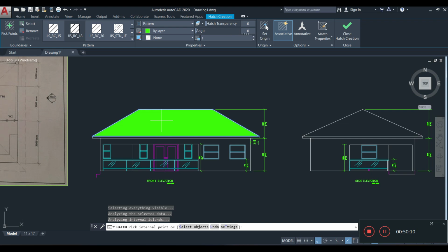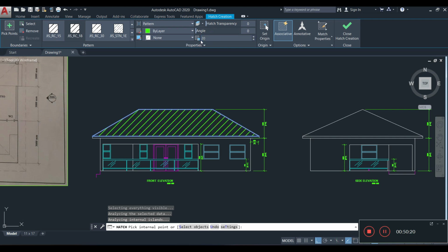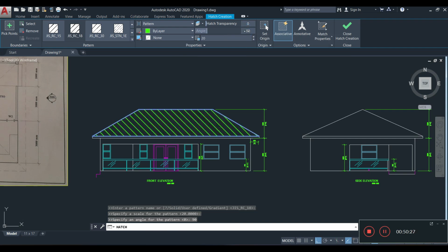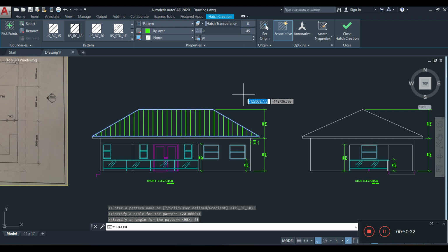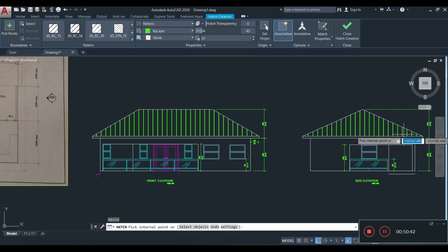Let's change the scale of this. Let's go 150. Yeah, that's too much. Let's go 20. Yeah, this can work. And the angle, I'm going to rotate it 90 degrees. No, that's not 90, that's 45. I was not paying attention. So something like that. That's what the standing seam roof will look like, that metal standing seam roof. All right. Same thing here. Let me go with that and enter. And add it here as well. All right, so that will be a roof.